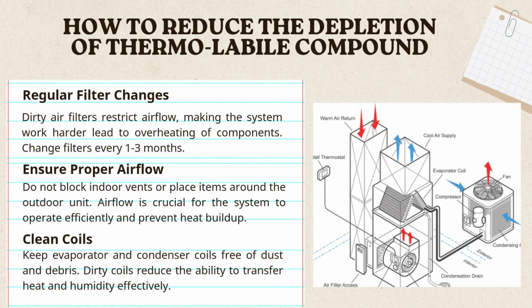First, we look at filter maintenance. Dirty air filters will restrict airflow, and when the airflow is reduced, the HVAC system needs to work harder. This will cause the internal components to heat up more than they should.